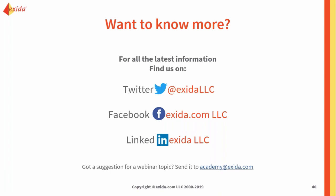You can have the top of the line everything, and if you just have one piece of equipment that isn't meant for this application or isn't the greatest, that one device can take out all of your other equipment and just make it useless. So ask for failure rates for the sensors, the controllers, the final elements, even mounting and bracketing, piping and tubing, all of those will make a difference.